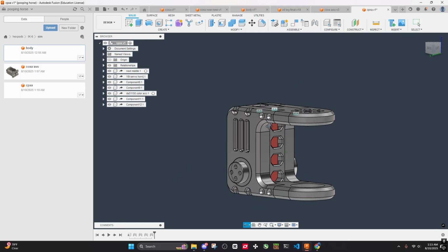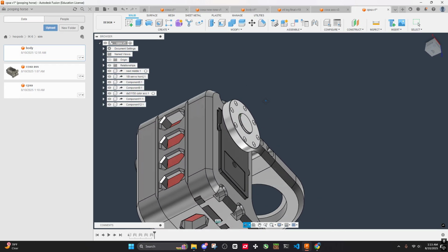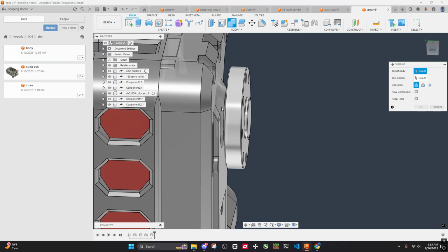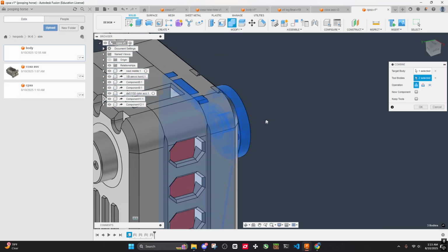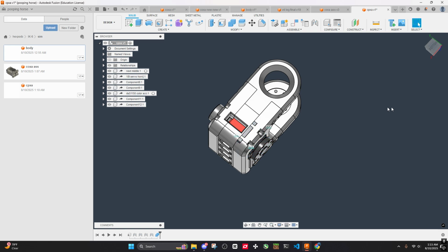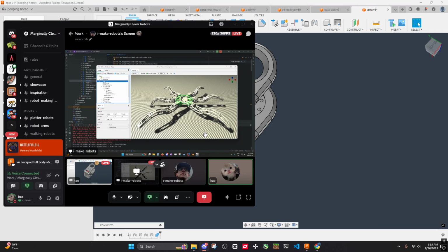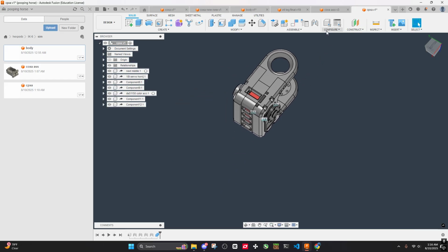I see. So it's better to get the algorithm working and then copy it onto the robot and make something happen. What would be the first goal? Would it be to make it walk, have a tripod gait? That's the most basic gait. The first goal would be to stand up and sit down without hurting yourself. I see. Okay. I had a way to stand up such that your toes are a set distance from the center, because I don't know where the ideal circle is, so I made it adjustable. If it's already standing up and you change the radius, it would pick up each foot one at a time and move it to the right position.